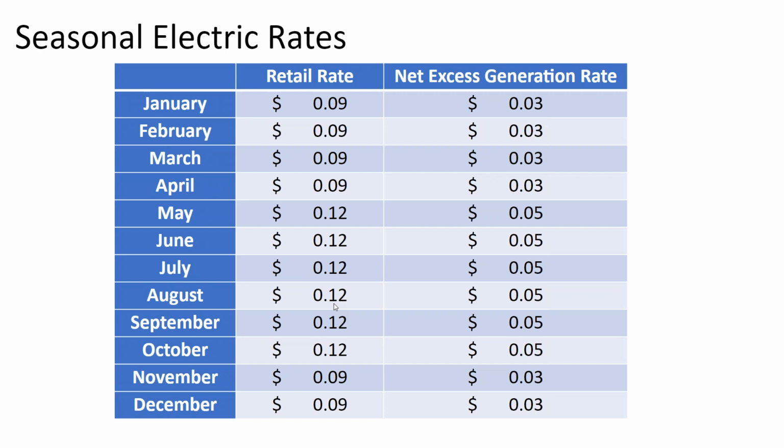But again, for off-grid residential, I'm usually around 20 kilowatts. And then there's certainly, when you get into larger residential luxury homes, 20 kilowatts grid tied is a starting point, and they can even go more than that. A 200 amp residential electric service panel is rated for 50 kilowatts of power. It's just not used all the time. So residential size solar arrays and residential size battery systems, for the amount of electricity that we use, are in the 12 kilowatt range on up.